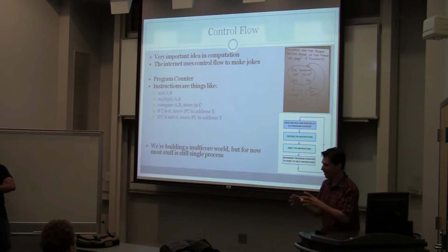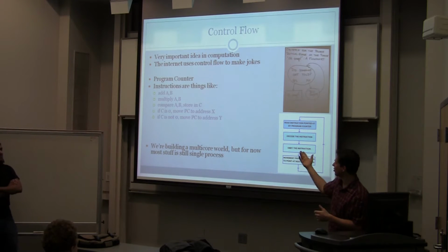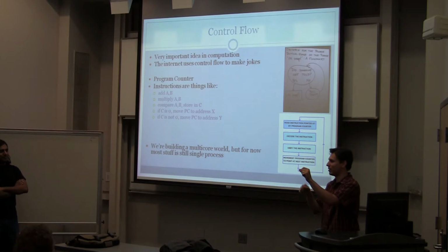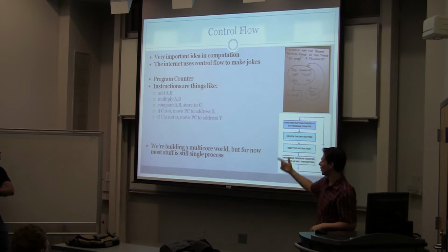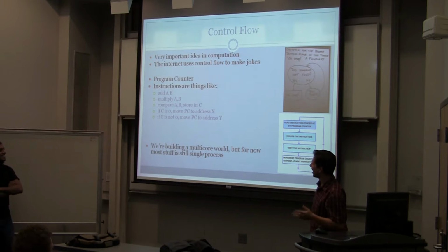So basically, inside your microcontroller is this thing called the program counter. It's just counting through instructions. And instructions are things like add one number with another number, and the way that's usually represented is add this register's contents to this register's contents and put it in this register. Or multiply, although your Tiny doesn't actually have a multiply. You can only add multiple times in a row.